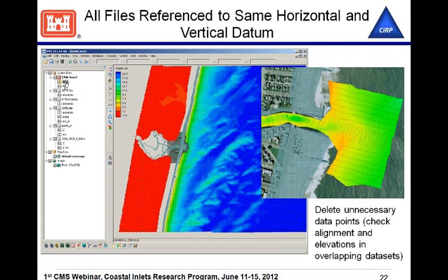So you bring all of these files in, and you see they're all listed here in the data tree. So we've got 1, 2, 3, 4, 5, 6 different surveys that are brought in, and we've made the various adjustments to them. So we have a data set here that's mean sea level in meters. We have this already came in as meters in 8083. We didn't have to do anything to this one. We have the coastal relief model, which we made a modification to, these others.